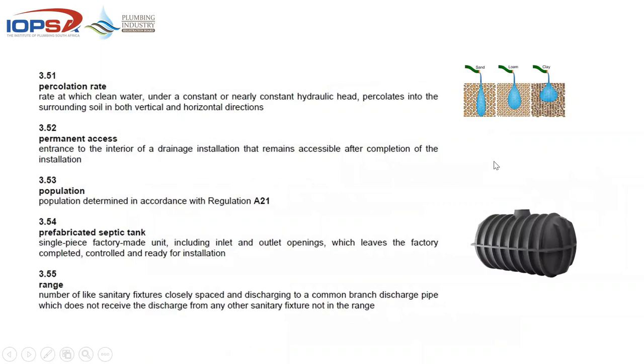Percolation rate, for the guys we spoke about non-waterborne drainage last time around. It is still required in areas that are not serviced, but if we are going to be doing it, we need to make sure there are formulas that you need to use to do the percolation rate calculation to see the size of the soakaway or the French drain or the evaporative bed, whichever term you want to use, that you need to have that information at hand.